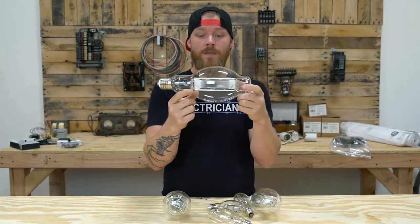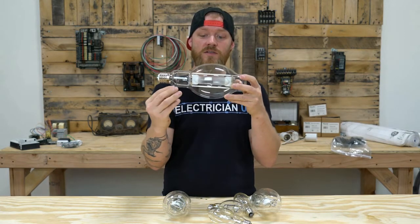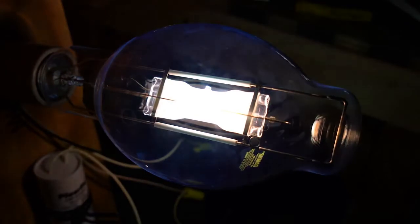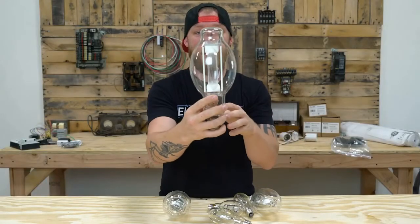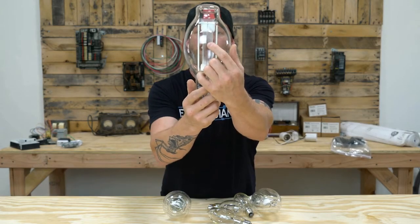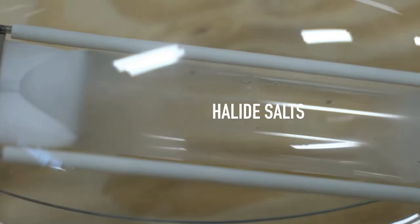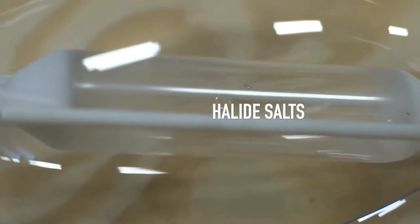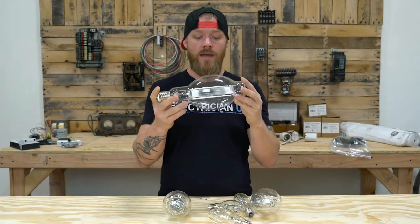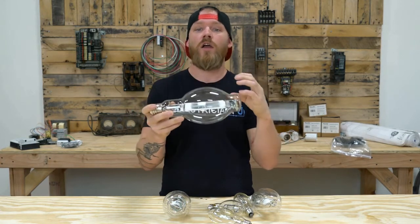And it's a really low blue color, so you'll notice when these first start to turn on that it's just this low, barely an arc at all. It just looks like a stream of low blue light, and that's the mercury. That's the color that mercury burns. Now in the inside of this tube, you have this cloudy kind of film all the way around that inner quartz tube. What that is, is halide salts. These are called metal halide lamps. So halide salts are certain chemicals that when vaporized, they will start to change color.